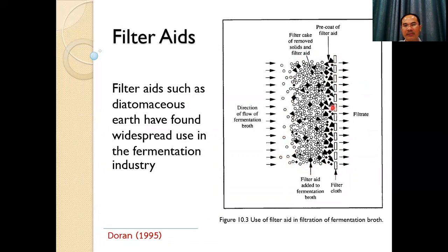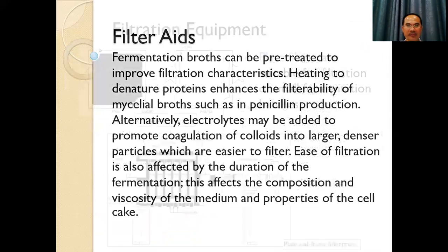The resistance to the flow mostly occurs in the filter cake because it's quite thick when compared to the filter cloth. So in operation we can neglect the effect of Rm, the resistance due to the filter medium, and consider only the resistance due to the cake. This is the assumption.